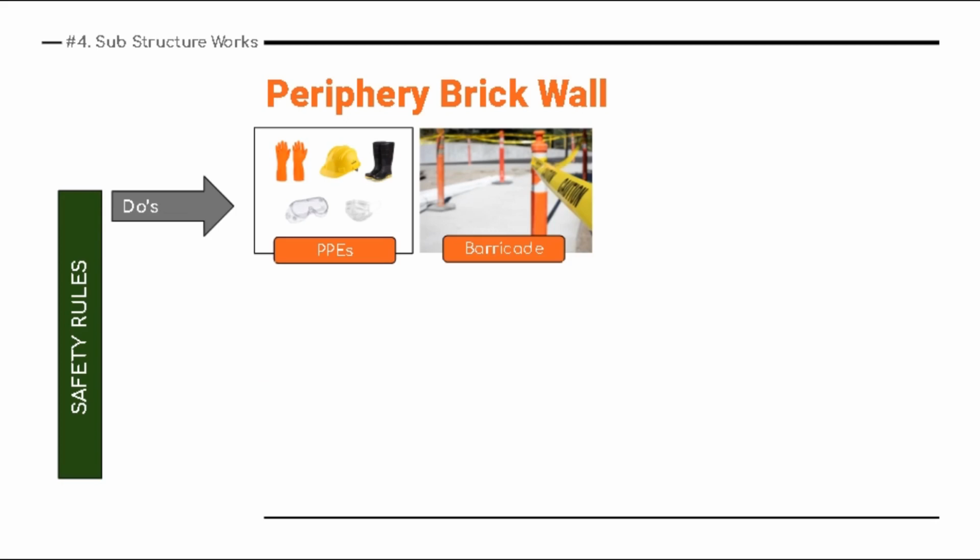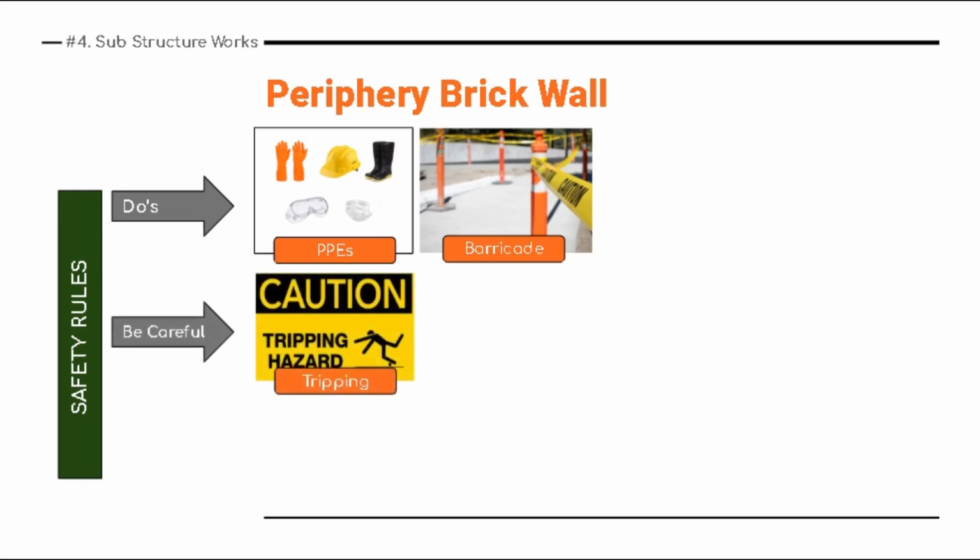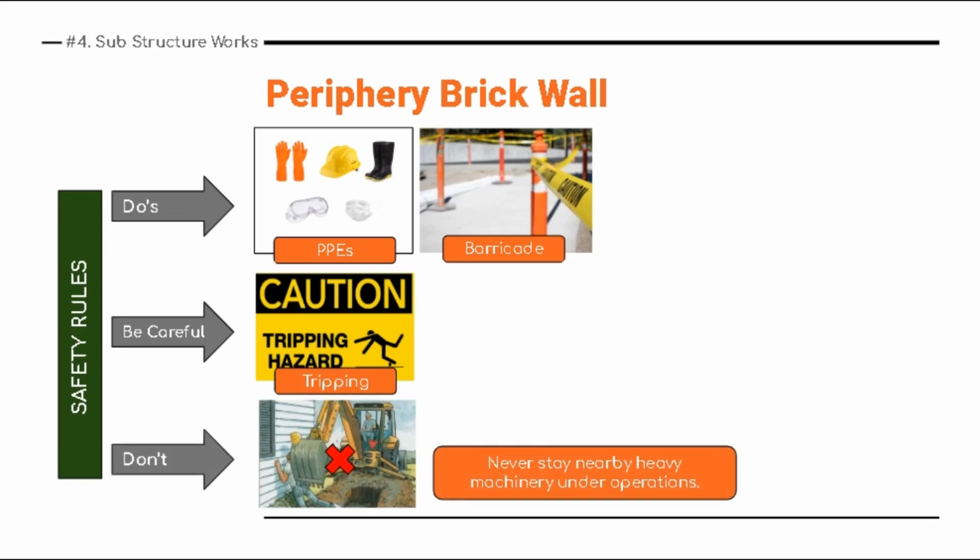Then there are always chances of tripping hazards as you are spreading the sand. Most of the time these are common at site, so be careful and never ever stay near any heavy machinery under operation, because you are using a mechanical backhoe excavator at site. Even when you're using the plate compactor, be careful regarding electric shocks. Okay, so check that the connections are proper. Everything should be clear.